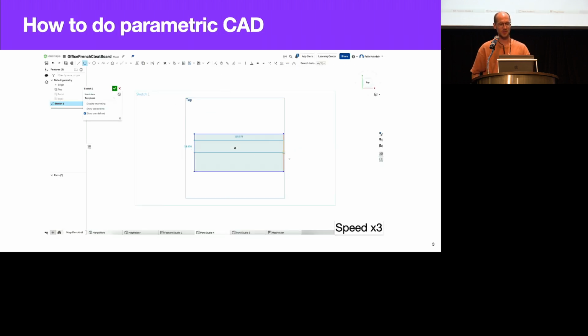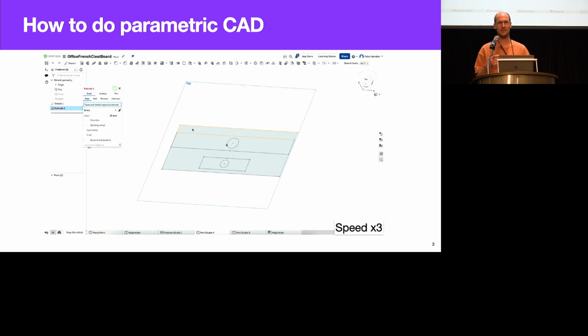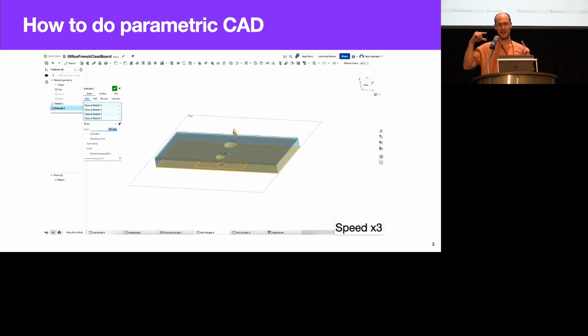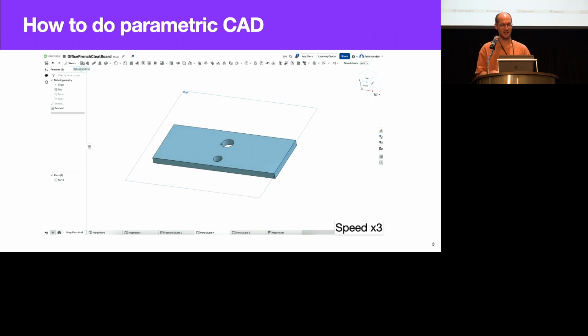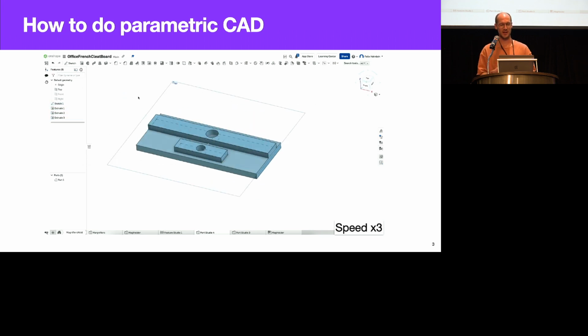This CAD model has been created in a dedicated software, here Onshape, for example. The usual workflow for creating these models is to start out by creating planar sketches out of simple primitives, such as rectangles and circles. These sketches can then be used by other operations to create or modify 3D geometry, as for example, these extrude operations.